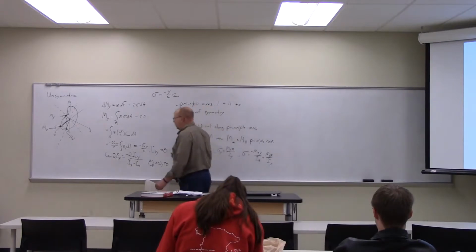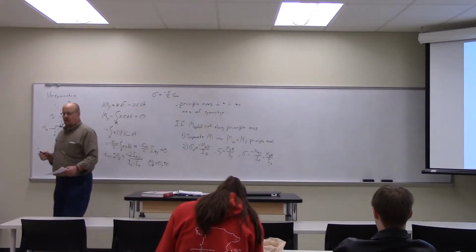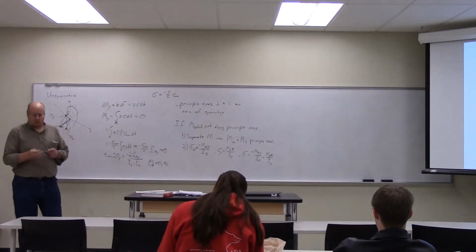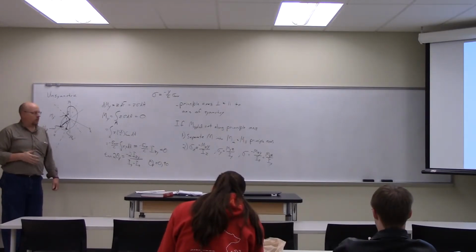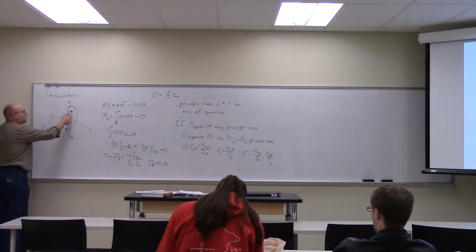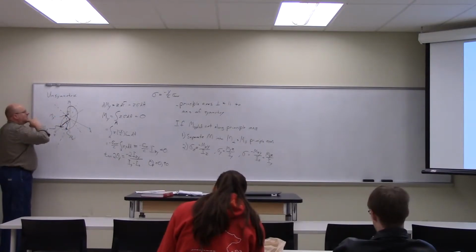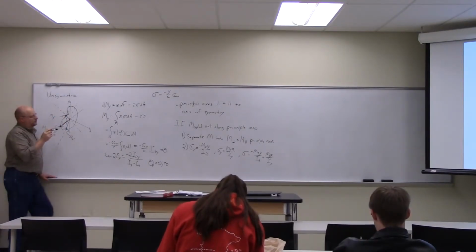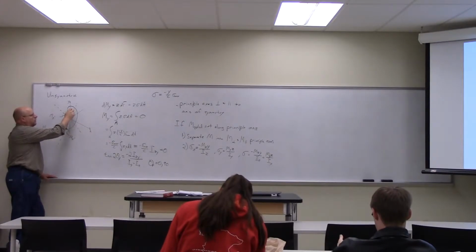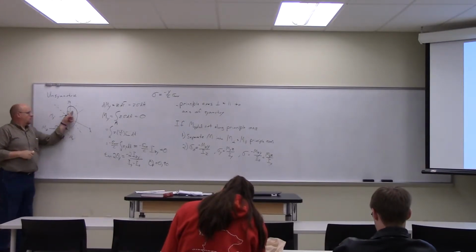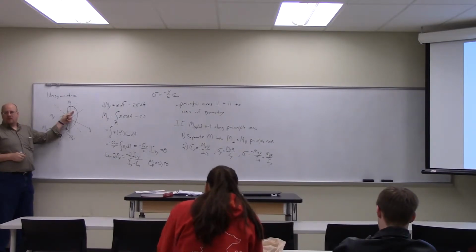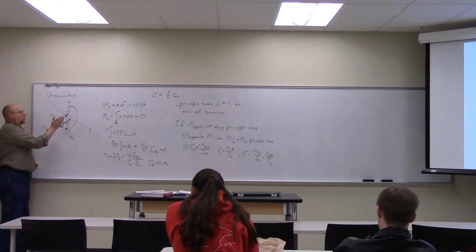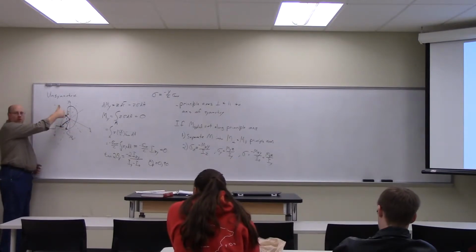And you notice that the first one is negative and the second one is positive. That's derived from the right-hand rule convention that we use for defining our axes. So if you look here, any force that acts in this region is going to create a positive moment in the y-axis.